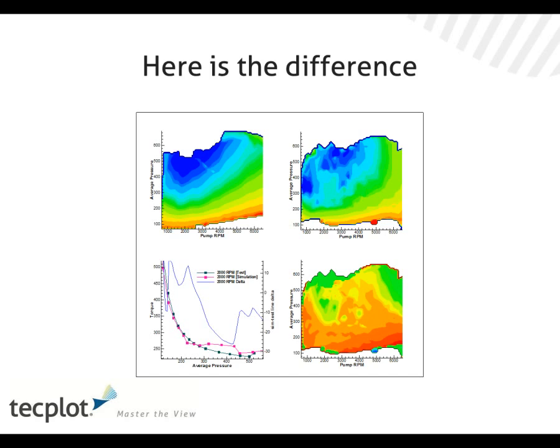One of the key things to point out here is that when you're looking at maybe more CFD data, and perhaps you're looking at pressure on an inlet, and you're trying to interpolate values onto a fine computational mesh, you really have to make sure that you use the right interpolation methodologies, because you may, in fact, run into some artifacts. Yeah, that's true.